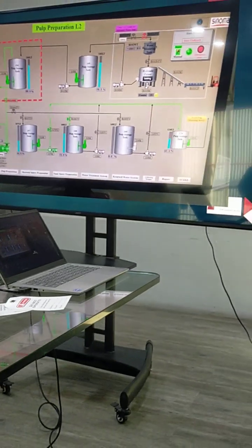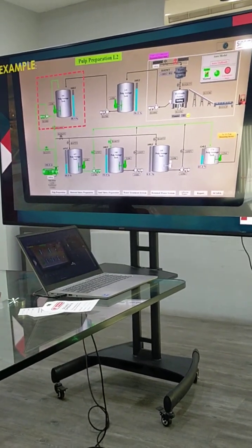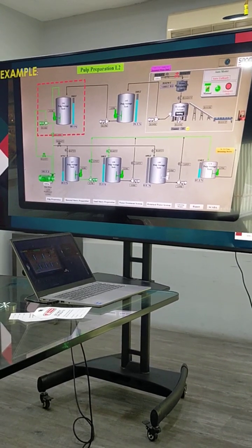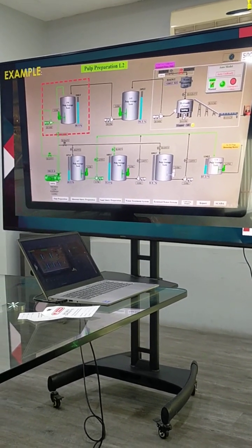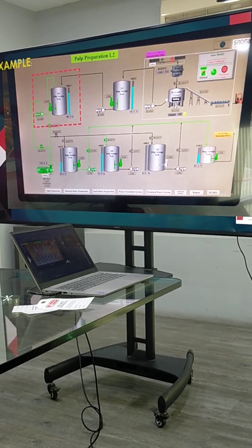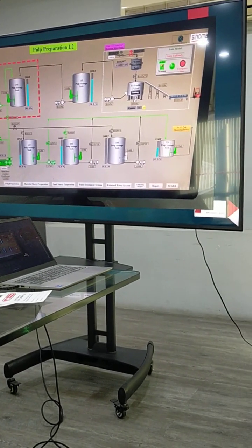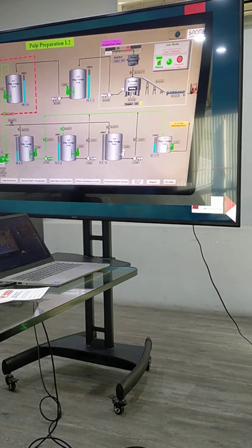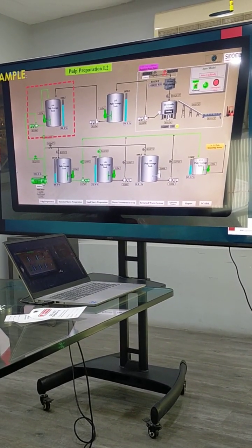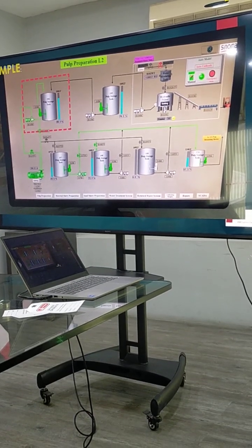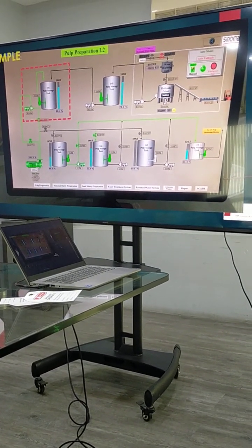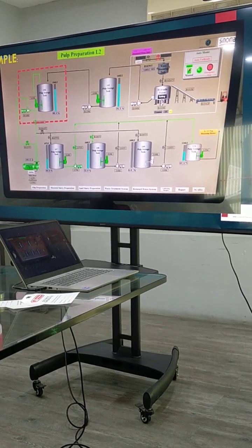I know we have trained operators who know where the circuit breaker is for their activity, so they will still do it. But in the long run, our goal is to have the isolator in place in the future, or have circuit breakers with a provision for the lockout, because this is very dangerous.